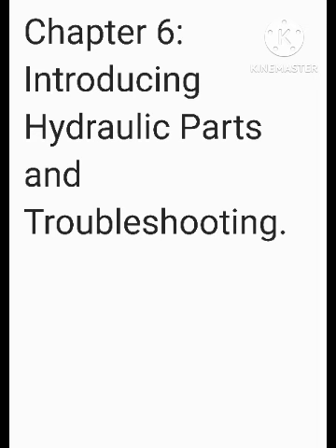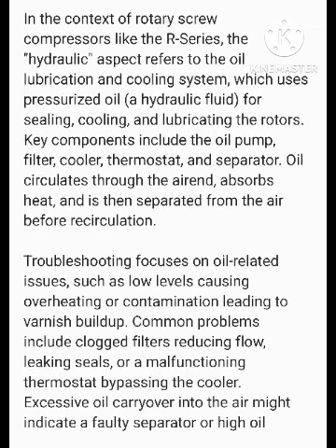Chapter 6: Introducing Hydraulic Parts and Troubleshooting. In the context of rotary screw compressors like the R-Series, the hydraulic aspect refers to the oil lubrication and cooling system, which uses pressurized oil, a hydraulic fluid, for sealing, cooling, and lubricating the rotors. Key components include the oil pump, filter, cooler, thermostat, and separator. Oil circulates through the air end, absorbs heat, and is then separated from the air before recirculation.